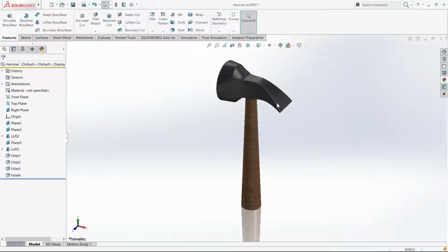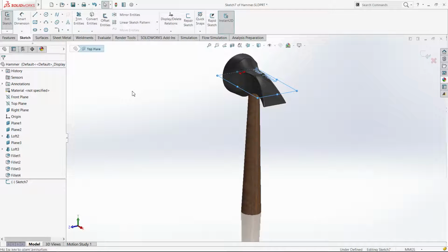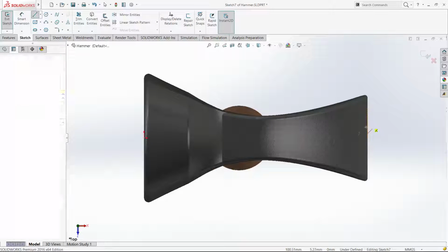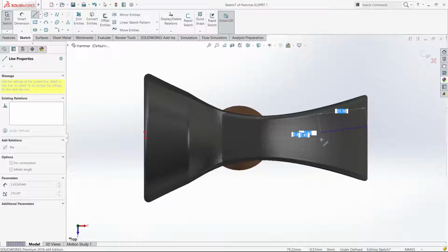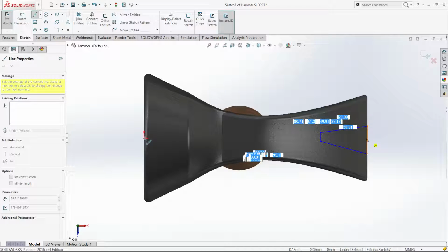So just for finish, I'm going to do that little hole you use for getting the head of the nails out. So I'm just going to create a cut. I haven't actually used the cuts, so they are pretty much the same as extrusions. It's just that instead of adding material, it removes material. So I'm going to create that shape using the same geometry as a reference.